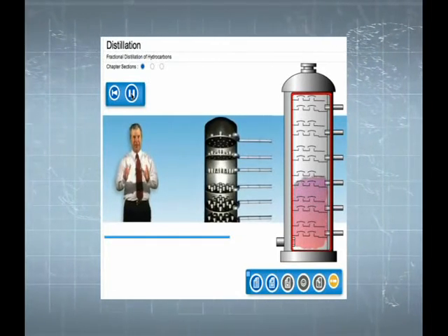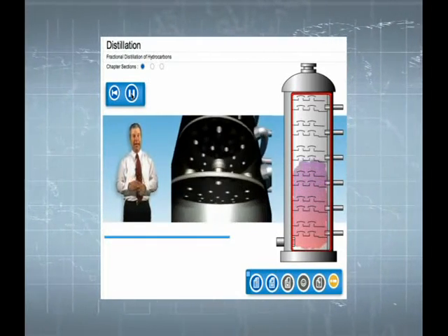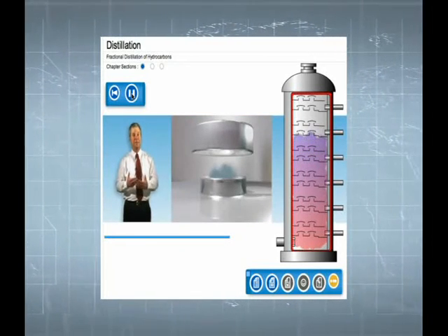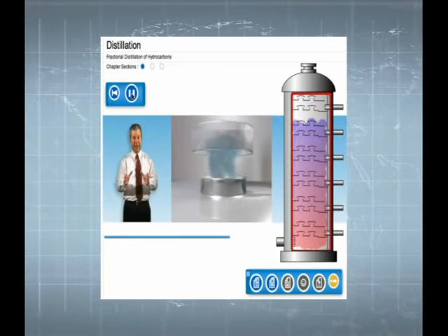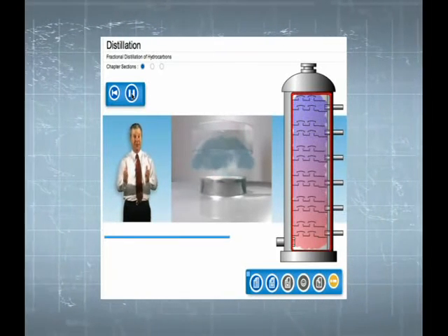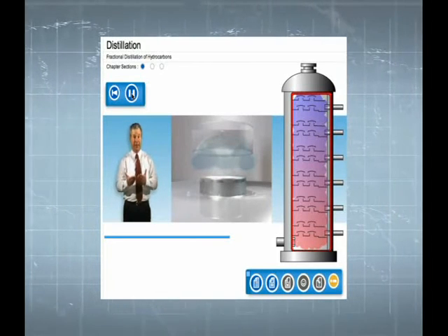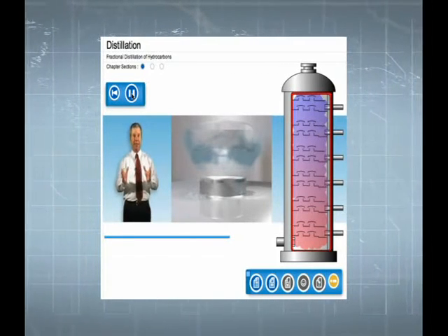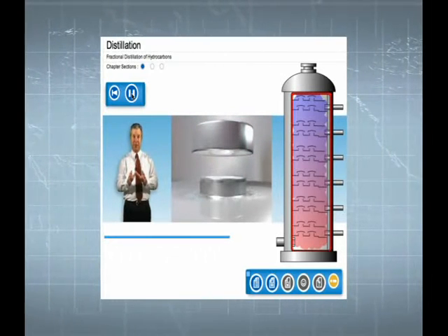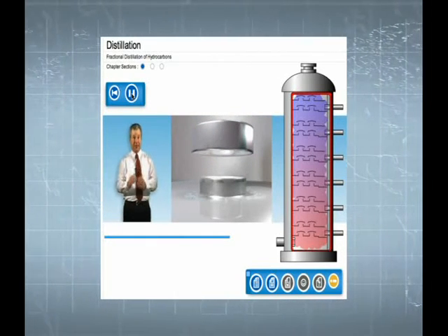The trays are set at varying heights in the column and have holes with condensing caps. These caps allow the vapor to make contact with the trays for a prolonged period as the vapor passes up through the orifice in the plate, collides with the cap, passes along the cap, and continues rising in the column. This cools the vapor, allowing some fractions to condense.